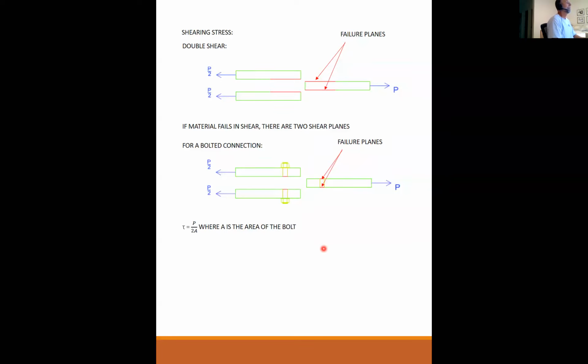But that's because in the seismic chapter, they've already made the seismic load a big load. And in the wind chapters, they made the wind a big load. So their load combinations are 1.0 each. There's icing loads, there's stressing loads from creep and shrinkage, there's truck loads, impact loads, rain load, ponding load, there's even a tsunami load.